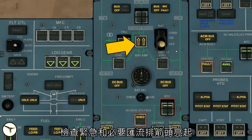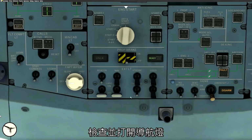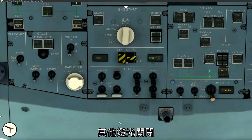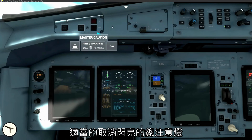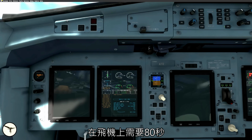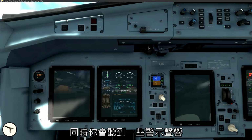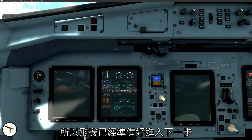And check that emergency and essential bus arrows are illuminated. Check there is no undervoltage light in the standby bus push button. When you check and set the now lights on, all other lights should be off. We cancel flashing master caution light when appropriate. Monitor avionics power-up and self-testing. In the aircraft it takes 80 seconds, and you will hear a few alerts along the way. But in this model, they have made a shortcut, so the aircraft is already ready for the next step.